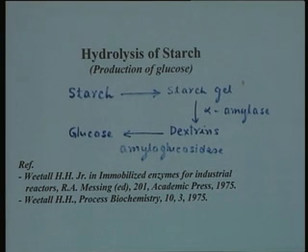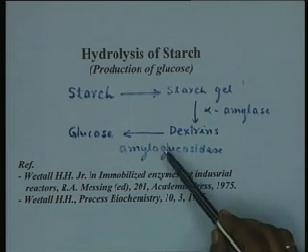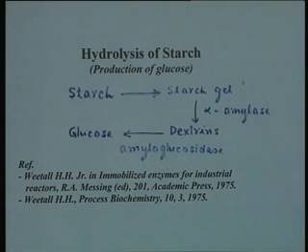But one of the major issues with the hydrolysis of starch is the viscosity of the feed, because starch hydrolysis is usually done at a very high substrate concentration, usually 30 to 40% dissolved solids, which makes a very viscous syrup during operation. This viscosity causes a significant problem as far as the pressure drop is concerned in packed bed reactors, and therefore not many packed bed reactors for this step are operational today, because use of packed bed reactors with almost 40% total solid syrup is highly energy intensive and is usually avoided.